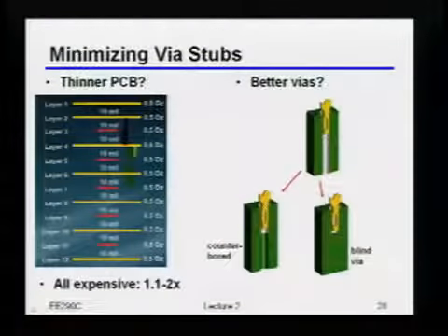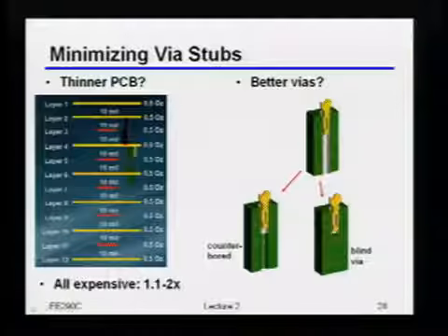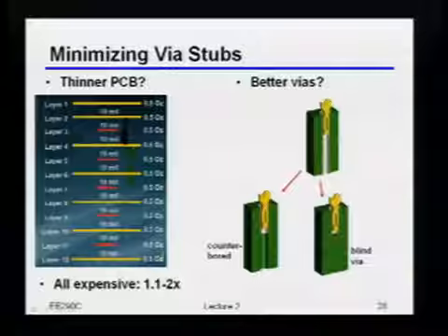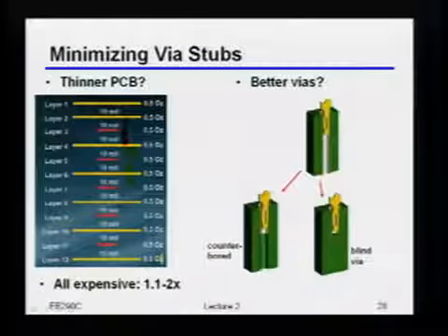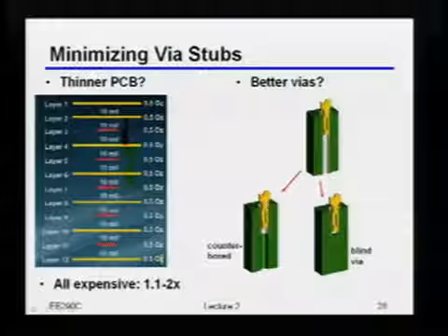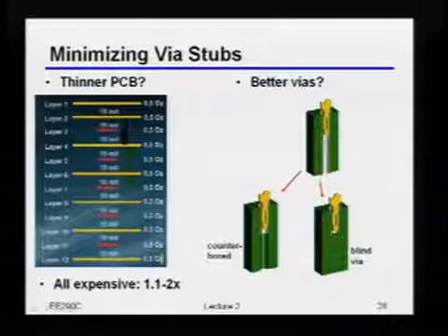So it turns out at some point it's actually almost physically impossible to do that, because you need a certain thickness of copper just to guarantee it actually flows through things sufficiently, etc. And by the way, as I've pointed out here, usually these things are like 12 layers or so just to be able to route all this huge mess of wires everywhere. So it's kind of tough to push too much on that dimension.